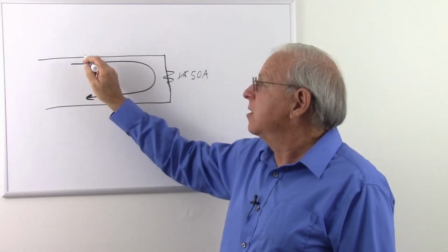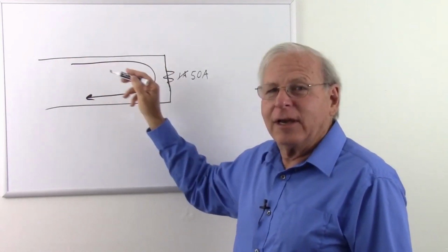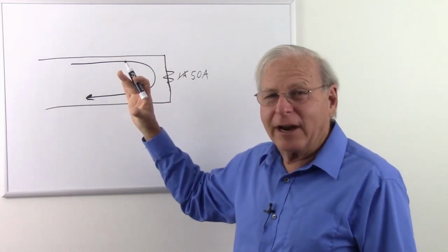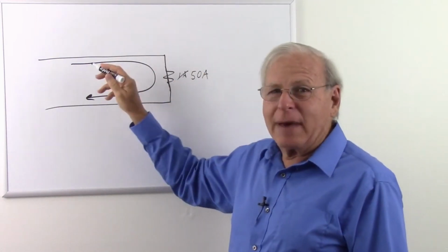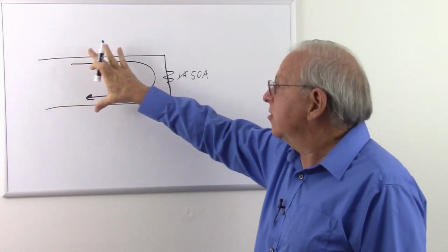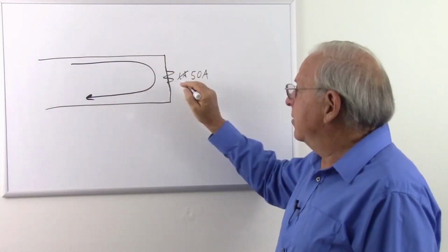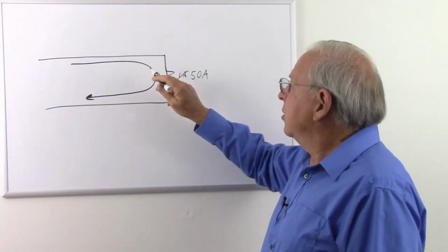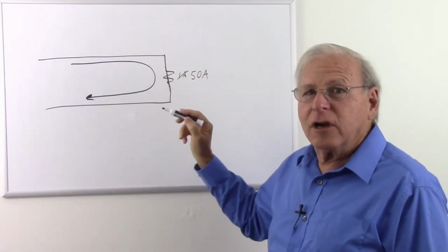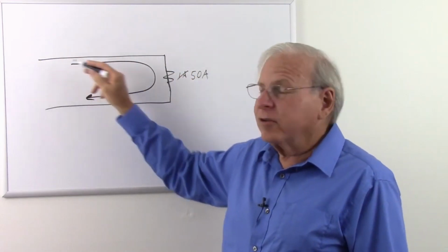So what's going to happen? We're going to get heat, we might get smoke, melted wires, and possibly a fire. So this is a bad situation. So we need to do something to protect this system from what happens if this fails. We think about fuses being there to protect the circuit, but the circuit's already failed. So what we are protecting is the rest of the system.